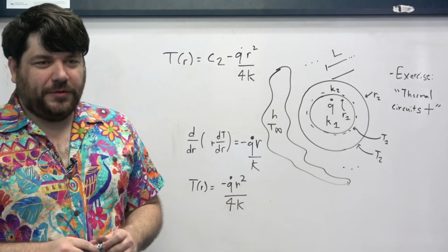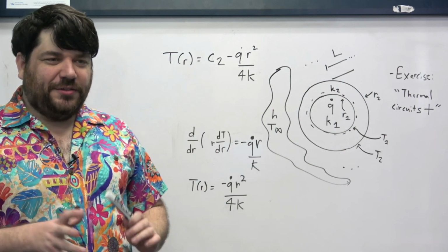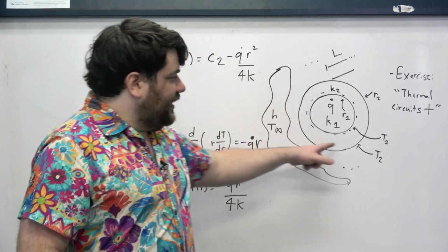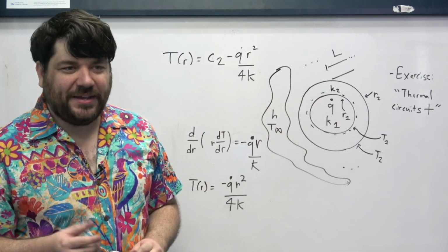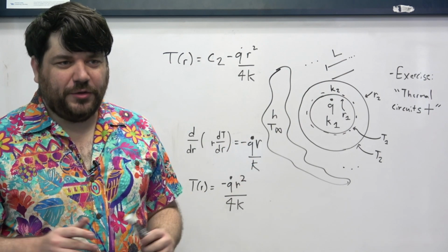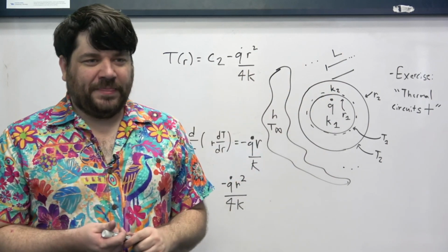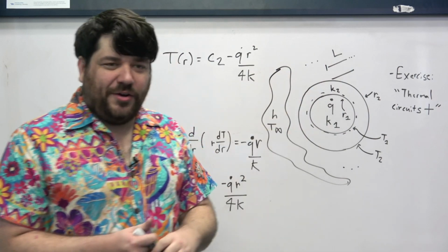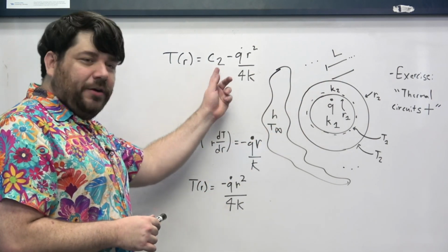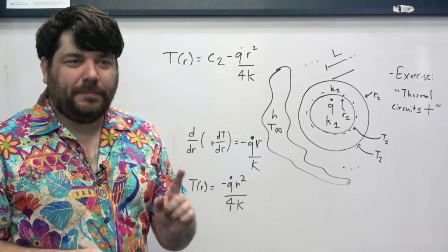And why is this meaningful? It's because it changes fundamentally the equation that tells us how the temperature actually changes with space. So in the cladding, the change is logarithmic. It decreases logarithmically, assuming that the heat transfer is happening outwards, which it has to be because of the q dot. So we assume that as you move outwards in r, in the cladding, the temperature decreases logarithmically. Here, the temperature is not decreasing logarithmically at all, it's decreasing parabolically.